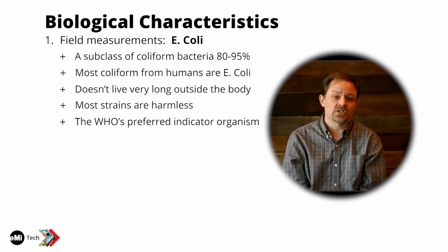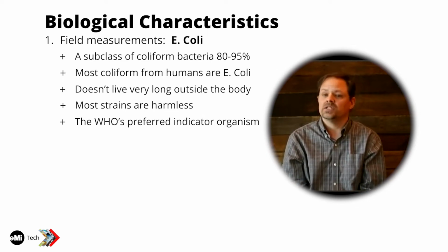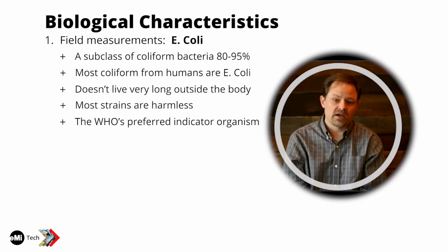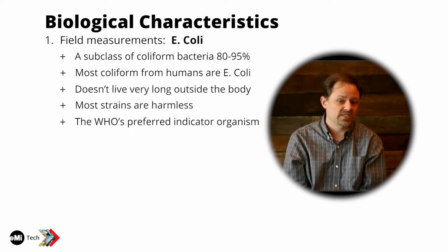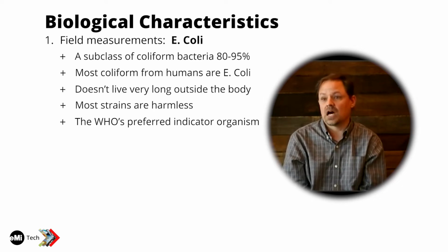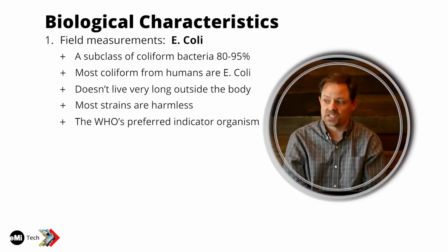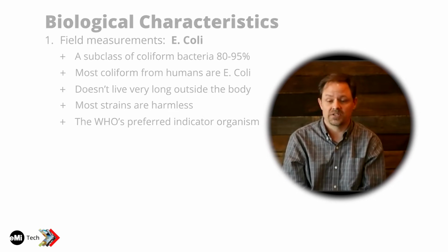But that being said, it's also now recognized that just because you have a lack of E. coli in the water doesn't mean you have a lack of other types of pathogens. It turns out that viruses and protozoa in the water also have a low correlation with the presence or the number of E. coli in the water. So really the optimal approach these days would be to use multiple indicator organisms to assess the water quality. But I think there's still a heavy reliance on E. coli, particularly in the applications that we're talking about today.